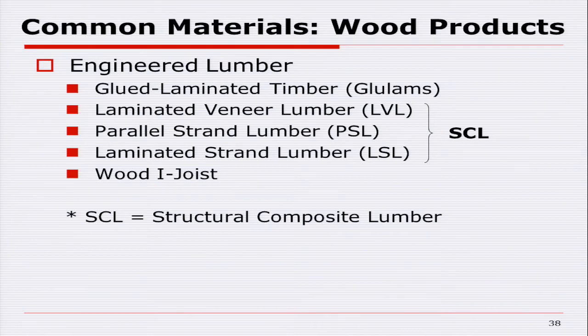So one of the issues with 2x4s and 2x6s and so forth is that they have undesirable lumber characteristics in them. At least they're undesirable characteristics of growth that reduce the strength for structural applications. And one of those is knots. Now, a knot is the result of a branch growing at that location on the tree.